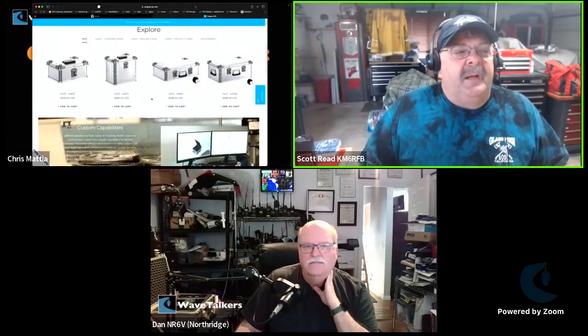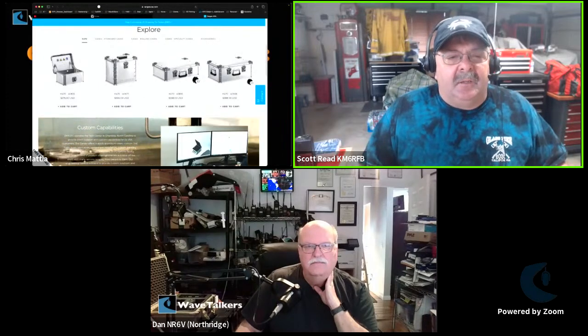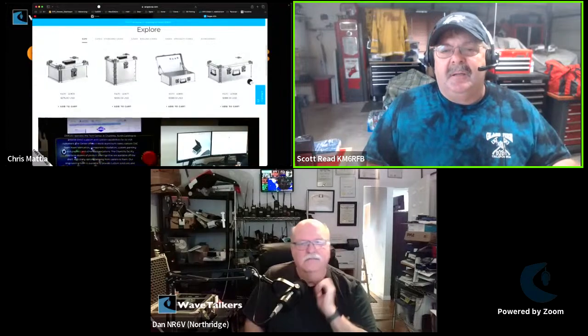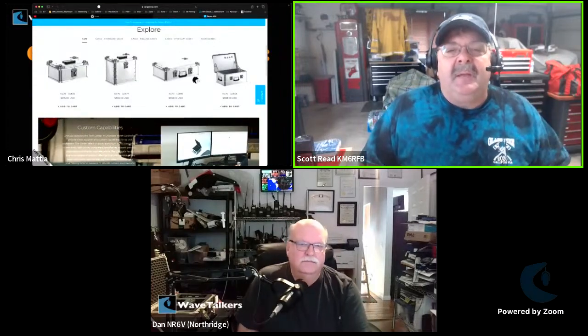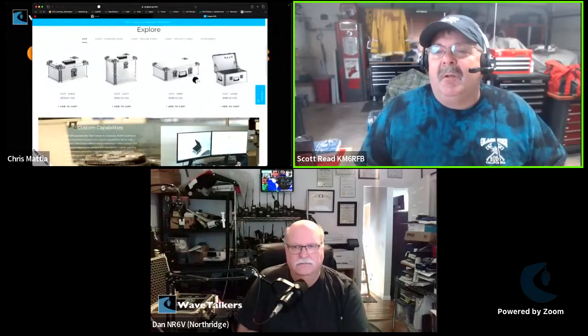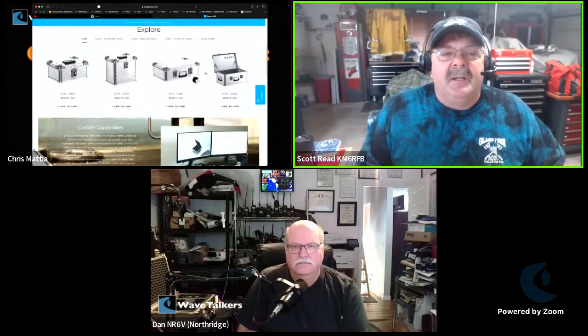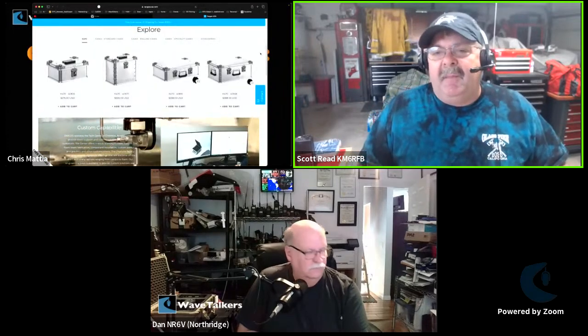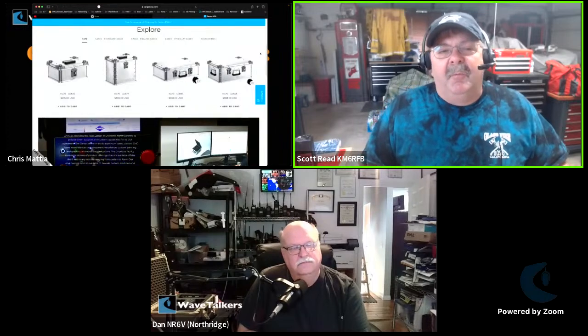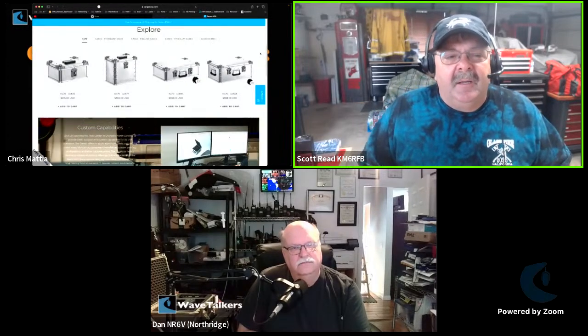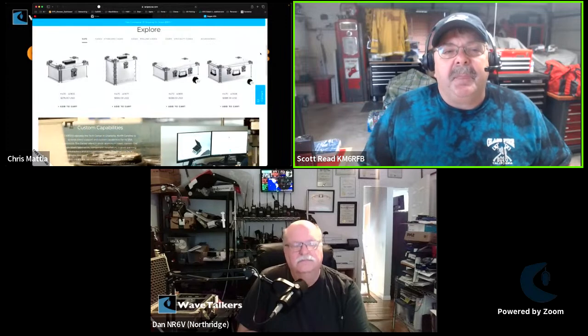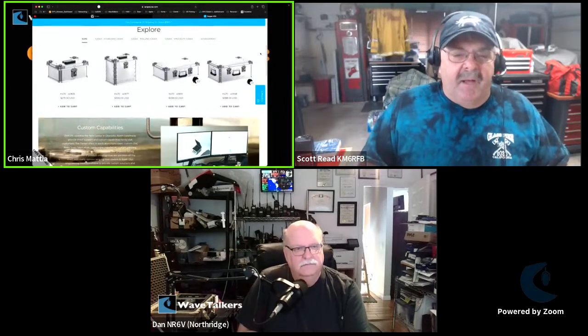And so what they recommend doing is taking aluminum duct tape that you would wrap around air conditioning ducts, and putting that over the seam. And what that does is it seals the portal through the box, improving the EMP on it. And then inside is foam. And then I put all my radio gear in anti-static bags. Yeah. And so now I've got an EMP proof box.